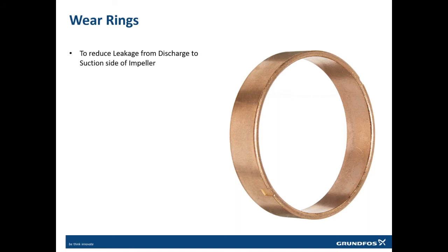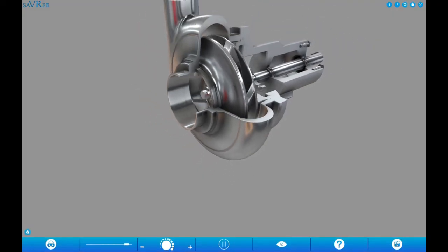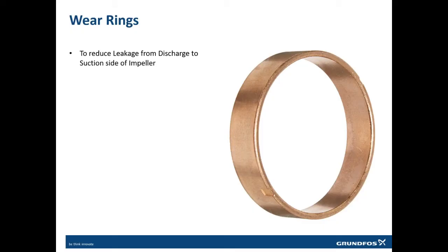By opening the tire, removing the brake pads, and installing a new one. The same goes for the pump. Once it is worn, you will just open the assembly, remove the impeller, remove the shaft, and change the wear ring. It is a consumable part. So this was the second component.